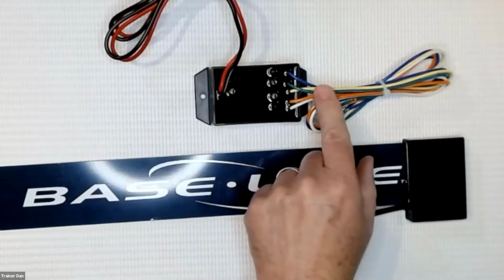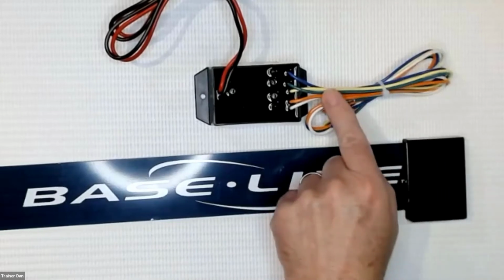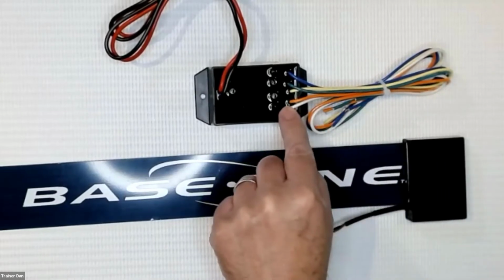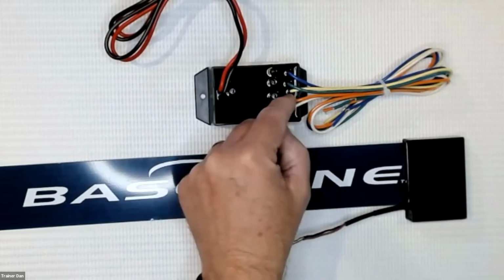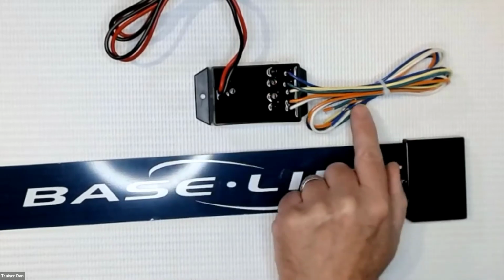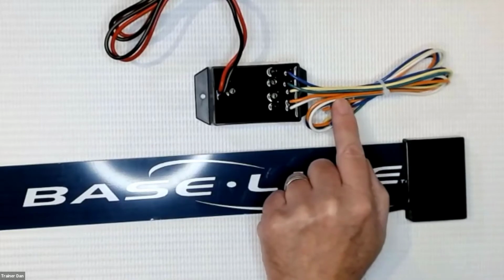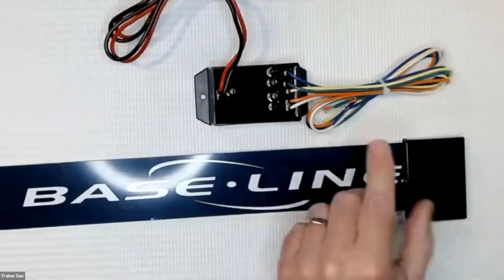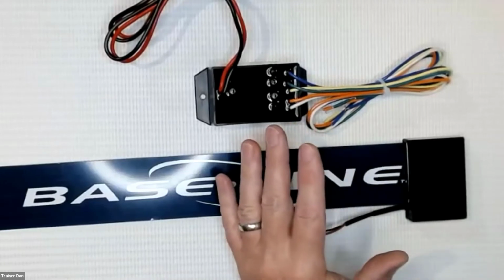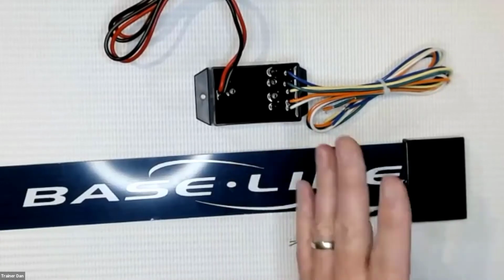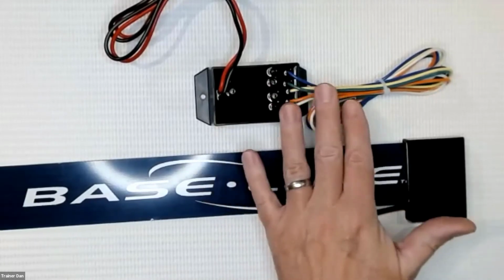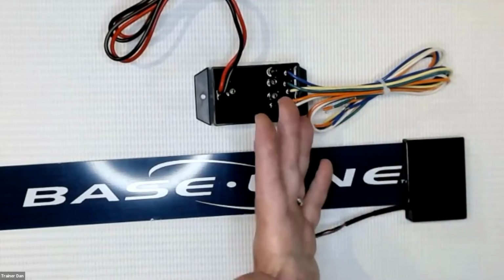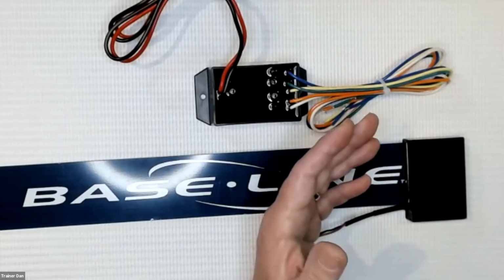There could also be problems on the solenoid side. These are going to connect onto the solenoids' wires. This is a 4-zone bicoder. So I've got a white common and then 1, 2, 3, 4 different wires that could connect to 4 different solenoids on this one. Any one of those 4 solenoids could cause an error, could cause a problem. It's not a problem for the entire system. It's just a problem for that individual zone. So it could be an open circuit, a short circuit. It could be the valve didn't work, different things like that.